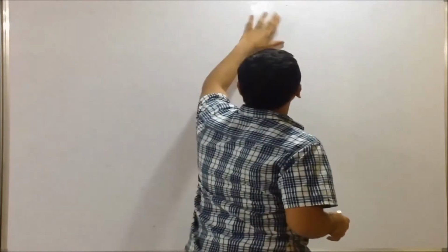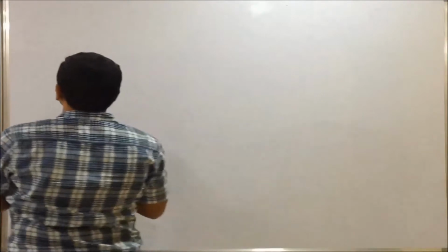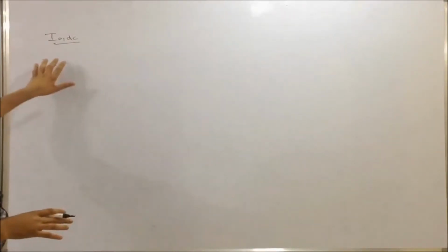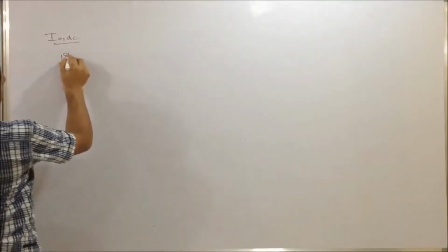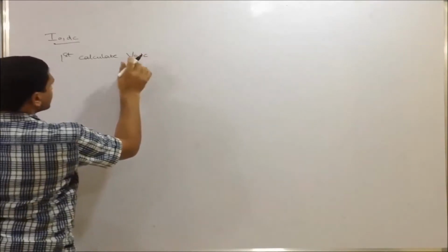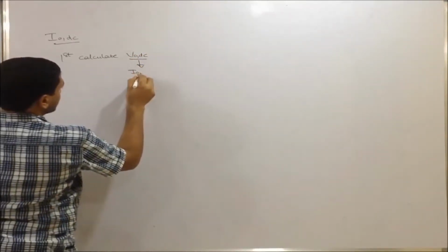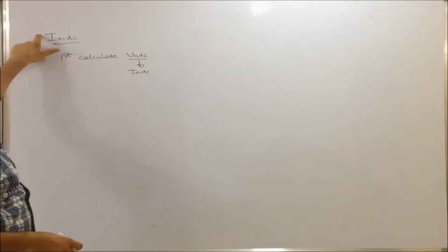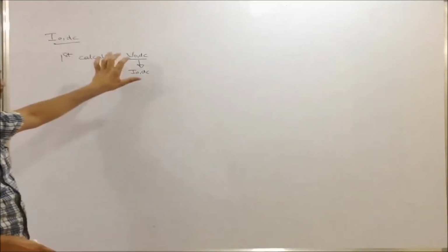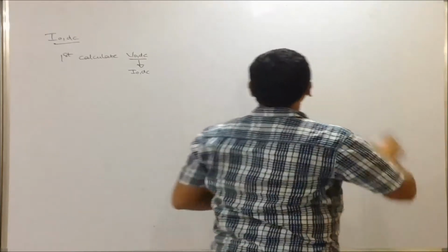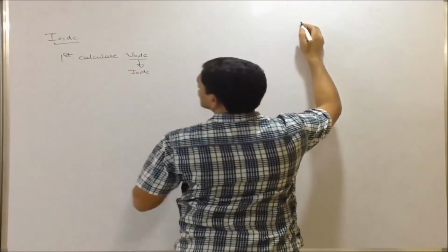Now you have to tell me what is I0 DC, because you have seen so many loads and you have calculated I0 DC in each and every load. So you tell me what is I0 DC. The first step is everywhere the same. First calculate V0 DC, and use this V0 DC for calculating I0 DC. This is the simplified procedure. Even after telling repeatedly, you want to calculate I0 DC directly. That is not correct. First you calculate V0 DC and then you calculate I0 DC. V0 DC comes through the generalized expression. Now, given V0 DC, we will find the I0 DC for RLE load.